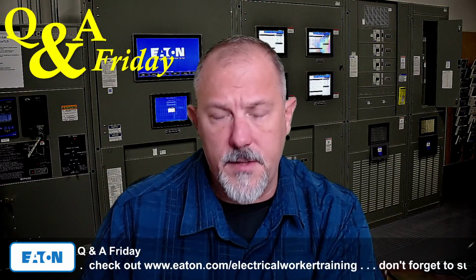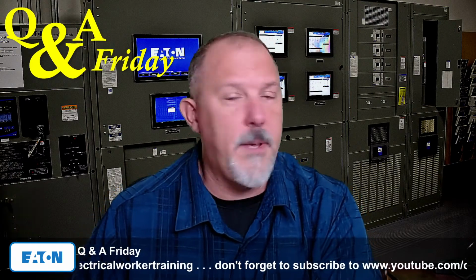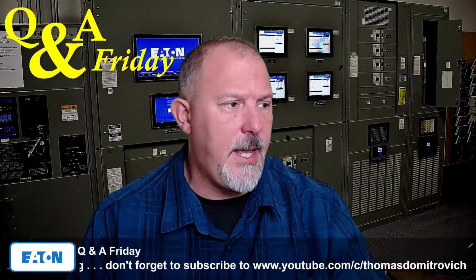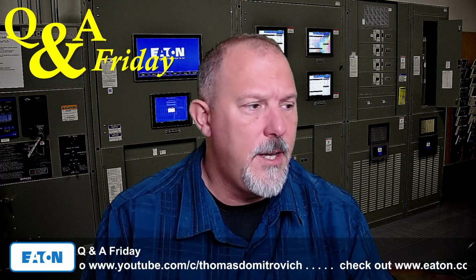So if you have a panel board on the secondary, you might have to have secondary protection to provide the protection for the panel board based on Article 408. But Navneet, I would say there's no requirement in the National Electrical Code that tells you that you need to do differential protection on transformers.